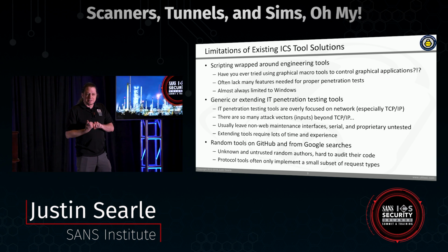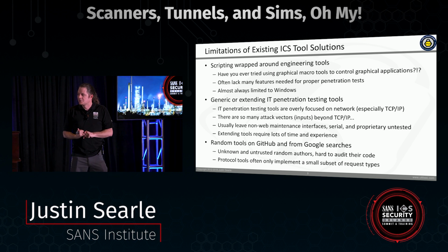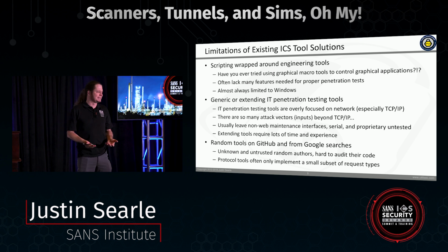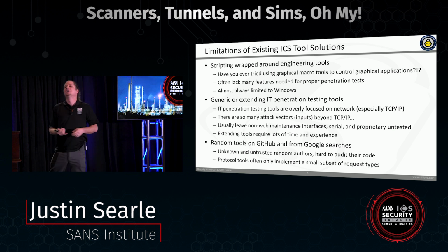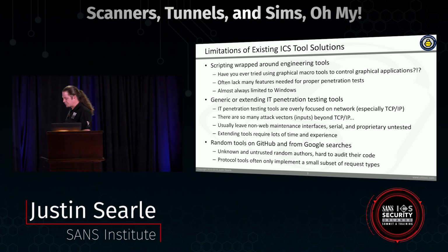Most of the IT pen testing tools primarily focus on TCP/IP, right? They don't understand the ICS protocols, and they don't address anything outside of TCP/IP. You would think, oh, well, a nice TCP/IP tool would work well with some of my Ethernet-only protocols, like GOOSE messaging. Yeah, sometimes it does, sometimes it doesn't. Depends on what you're trying to do with GOOSE. So that becomes a bit of a challenge for you.